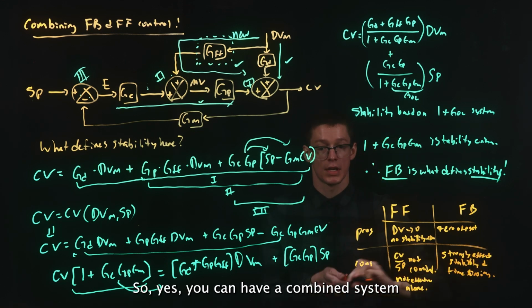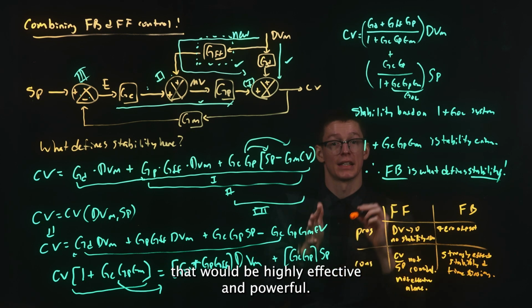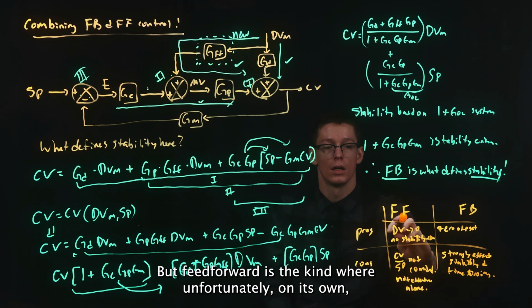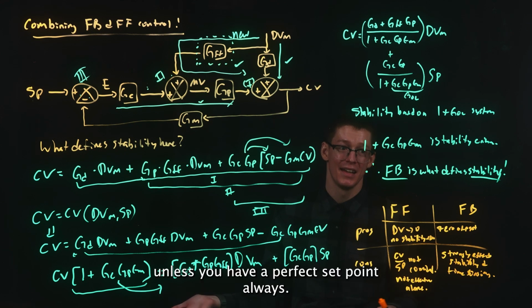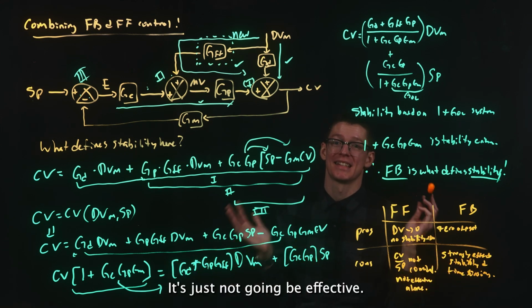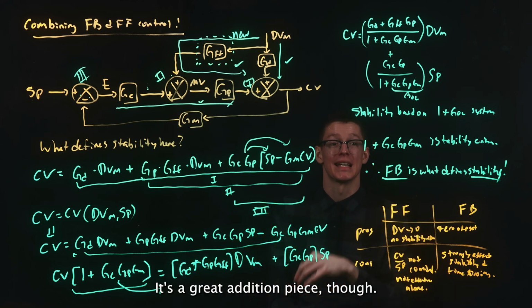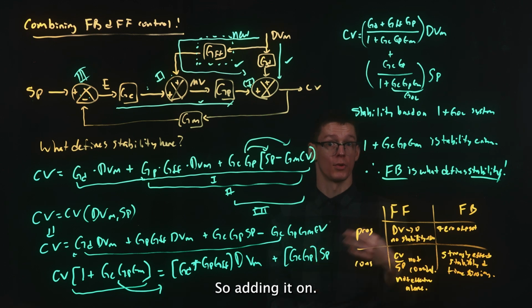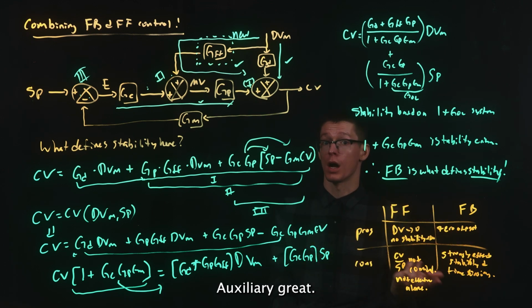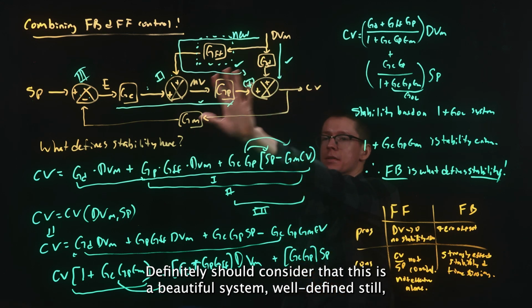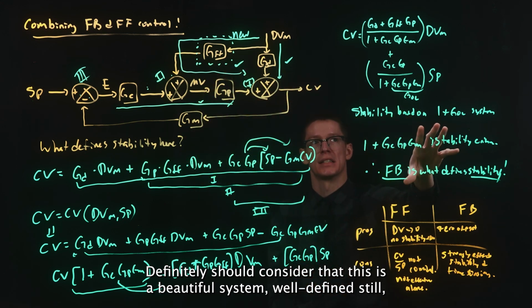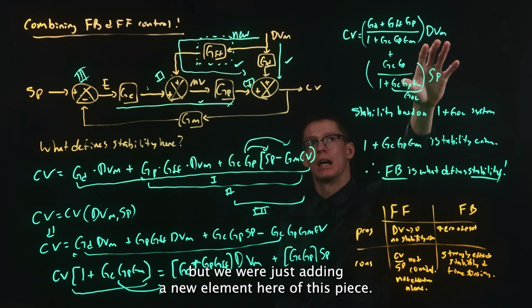So yes, you can have a combined system that would be highly effective and powerful, but Feedforward is the kind where, unfortunately on its own, not very effective, going to be honest. Unless you have a perfect set point always, it's just not going to be effective. It's a great addition piece though. So adding it on auxiliary, great. Definitely should consider that.